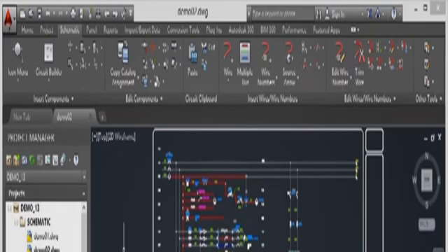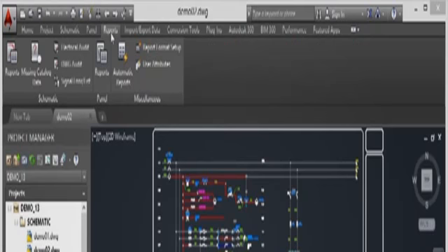Where do you find the DWG audit command? It's actually on your Reports tab here on the ribbon, and it's this command here, DWG Audit. What it does, as it says there, is it detects problems related to wire numbers and wire connections, and displays a report of them and any repairs it might make. Drawing Audit identifies and cleans up some of the problems that can affect an AutoCAD Electrical drawing. You can also save the error report for reference or surf the file to view and correct the errors. So let's have a look at that.